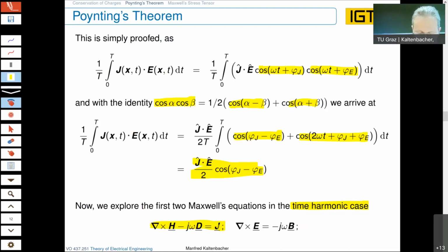which means, since I put it to the left-hand side, we have here the curl of H. The underline always means we are now in the complex domain as well, which is equal to the frequency domain, minus, clearly because we have put it from the right-hand side to the left-hand side, j omega D is equal to the current density.